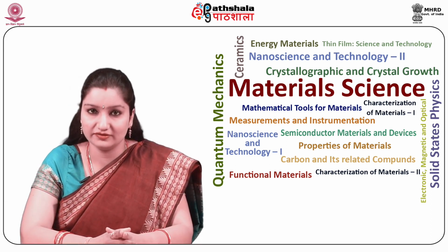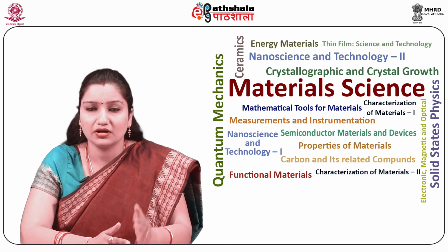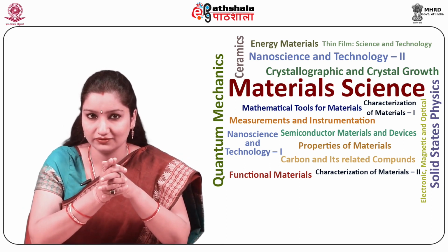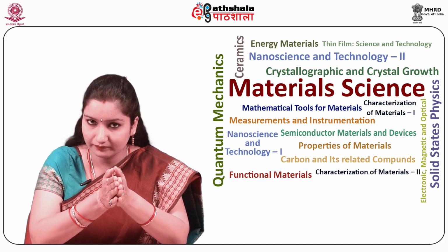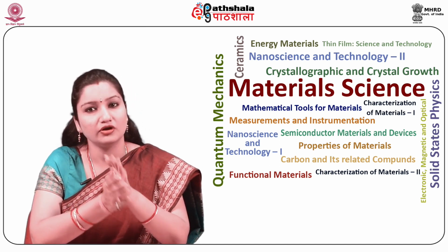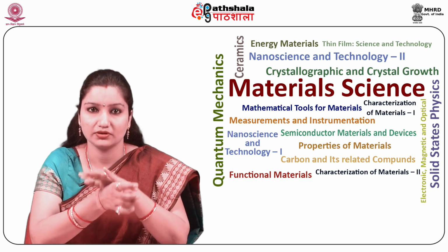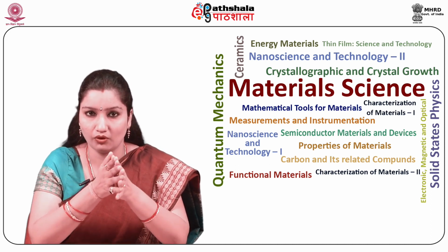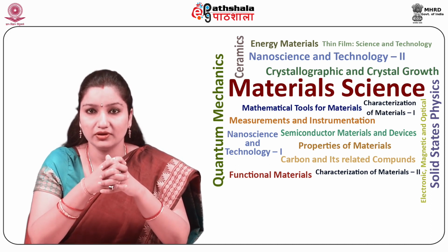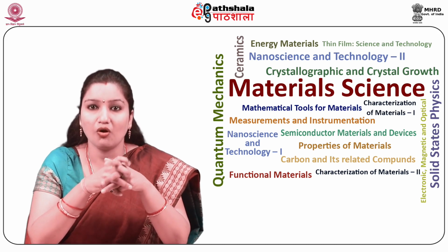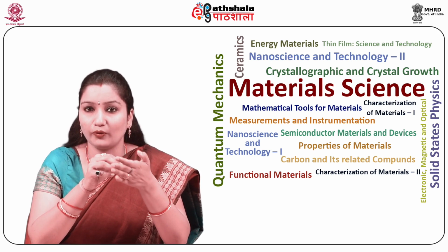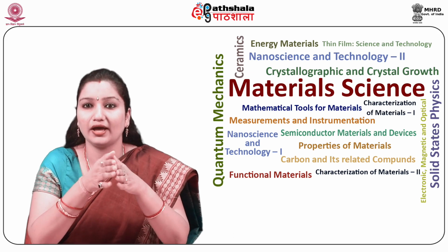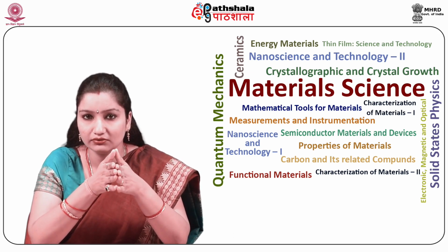Next is the Rockwell hardness test. The Rockwell test constitutes the most important method used to measure hardness because it is so simple to perform and requires no special skills. Indenters include spherical, hardened steel balls having diameters of 1.588, 3.175, 6.350 and 12.70 mm, and a conical diamond, which is a Brale indenter, used